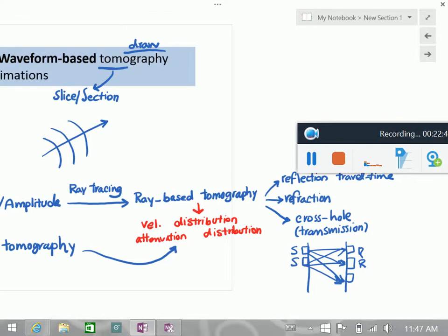And then there's a downhole test, right? So if you have a downhole test, your source is up here, and the receivers are here. And that's just one borehole. Here you don't have a tomography unless you have several sources. Here you can have several sources, and then you can map the velocity in the area between the sources and your receivers. I just want you to see that NDE and site characterization are very, very similar. It's just different scale. So there is always an equivalent of one to the other.